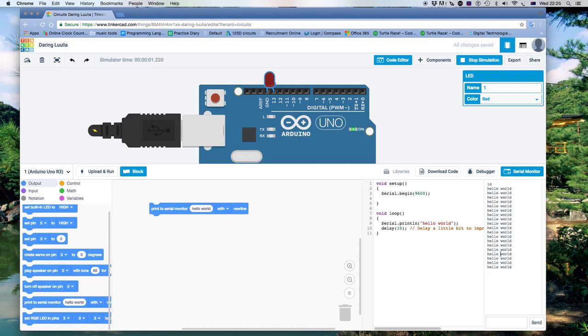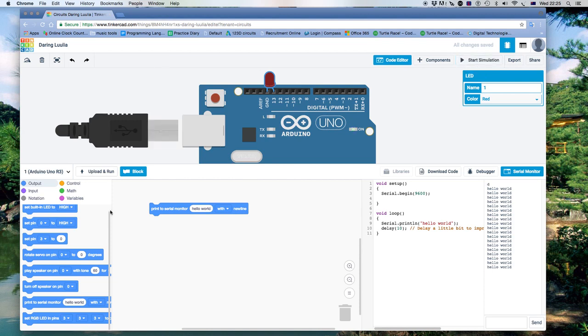So I was saying hello world, it's printing it out, Serial.println, that's l n, that looks like in, but it's ln, that's line, and there's a message. I can print anything out. I'm going to stop that now. Let's see if we can add a bit of a delay so it's not going quite as fast.